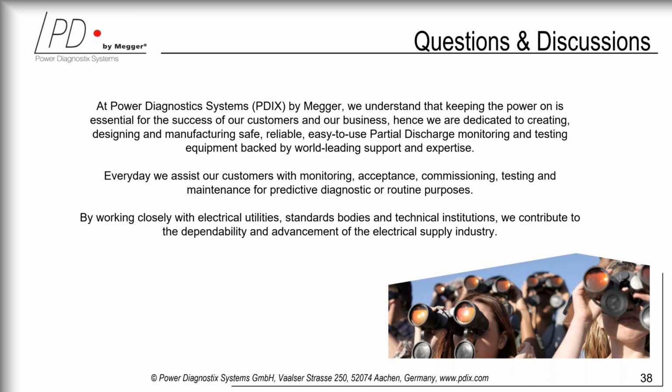So the first indication would be a level higher than this acceptance level, or a level higher than the noise floor level. So what we do, we calibrate the system in the field, and then we set the warning and alarm levels 30% higher than the noise floor, which should be much lower than the acceptance level that we know from the factory.